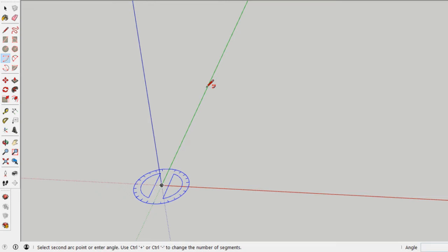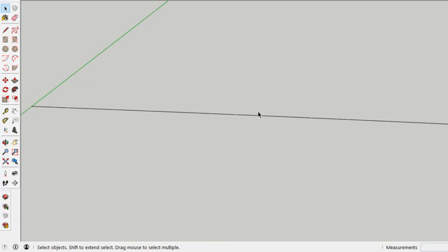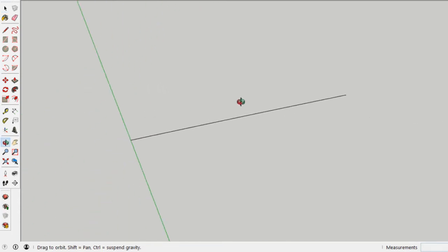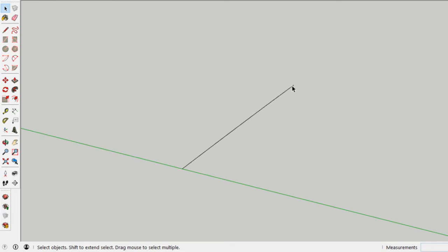Now it says angle. To make the Earth, we need a section of the Earth. We just need 1 degree of angle. 1 and enter. Now it disappears. If we take that zoom extents here, it pops back into view. This is a section of the Earth. This is 111 kilometers long. This is 1-to-1 size of the Earth. 69 miles or 111 kilometers. 111 kilometers, 193 meters and 52 centimeters.